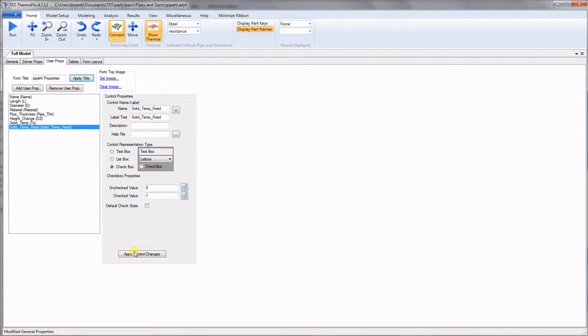And the very last property that we want to define, we go ahead and add the number of nodes that we may want to put in analysis. So we just call it nodes. And the label, we call it number of nodes. And this is unitless, and we default value 3, and apply the changes.